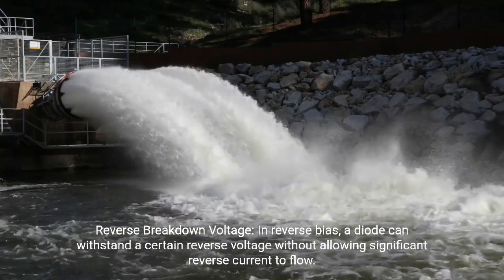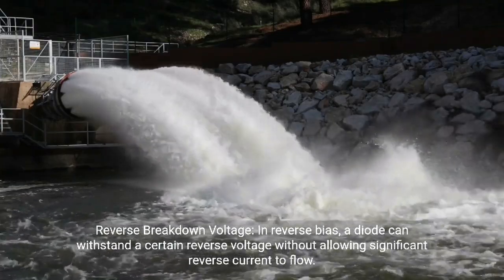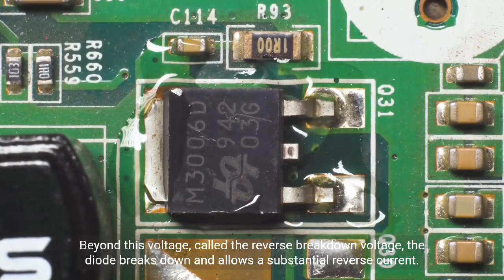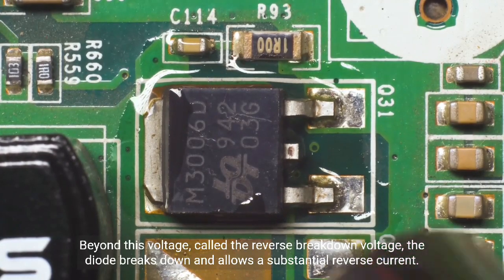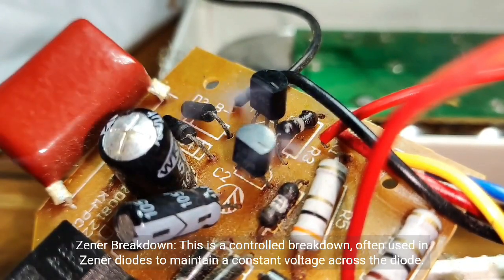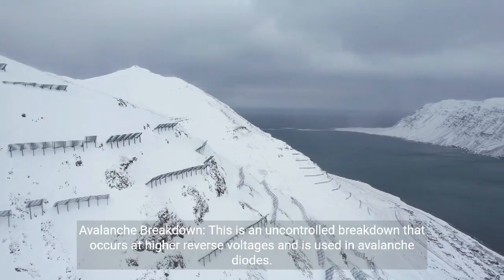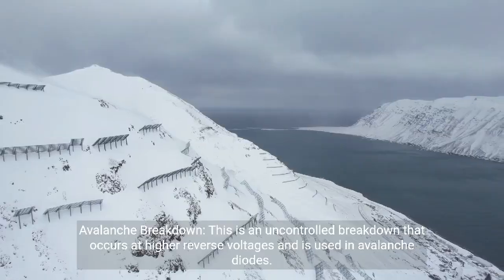Reverse breakdown voltage. In reverse bias, a diode can withstand a certain reverse voltage without allowing significant reverse current to flow. Beyond this voltage, called the reverse breakdown voltage, the diode breaks down and allows a substantial reverse current. There are two types of breakdown. Zener breakdown: this is a controlled breakdown, often used in Zener diodes to maintain a constant voltage across the diode. Avalanche breakdown: this is an uncontrolled breakdown that occurs at higher reverse voltages and is used in avalanche diodes.